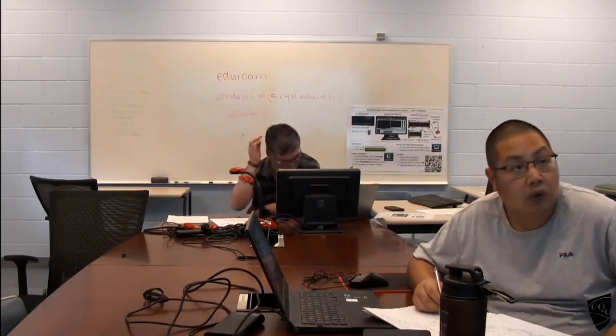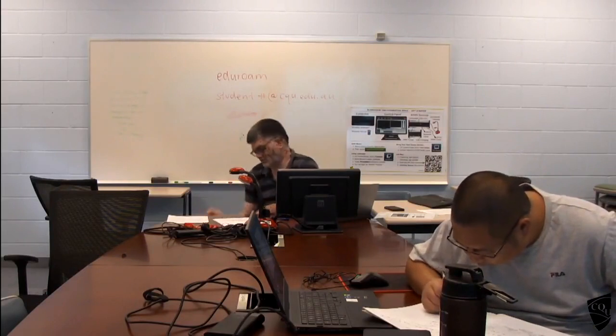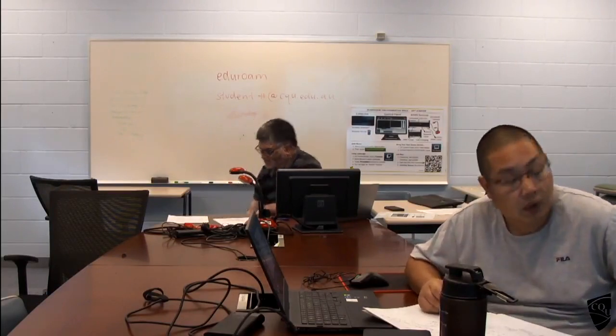Here I don't put N minus 1 because we don't need to fill, everything is empty because there is no concrete below that line. So you can put N times AST. So earlier one part of the AST went to fill the holes in the bottom concrete area.